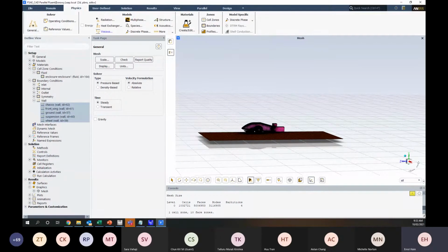For grid independence, another question. For grid independence analysis for different turbulence models, should we use different near wall region mesh resolution? For example, in comparison to K epsilon wall functions with K omega SST. There are some idiosyncrasies with the different models, and I will cover those at a later date. But understanding what kind of Y plus value is really important. We'll go through what Y plus is in a bit, but there are some different grid resolutions that you would use for different models.